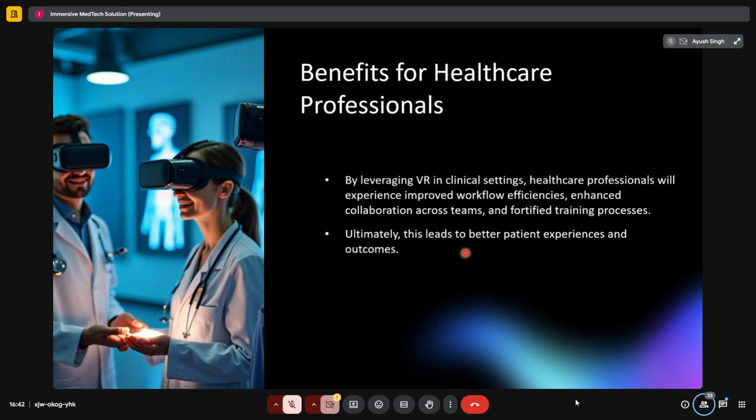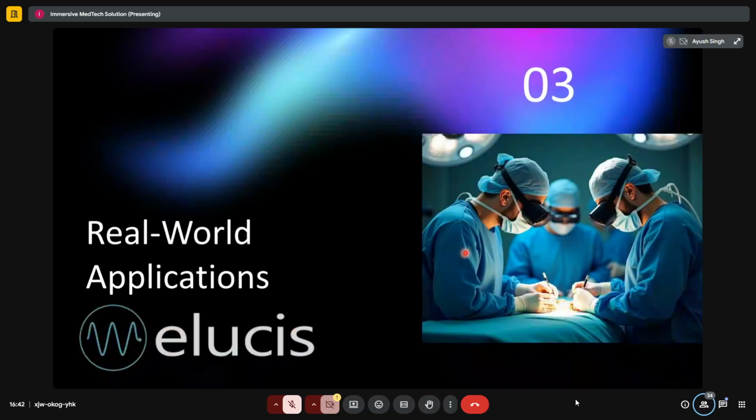After that, we also have certain levels of segmentation. We have low, medium, then high, then ultra. These are different settings that we can select. Generally the preferred methods are medium and high, because the higher the value goes, for example with ultra, we will require a decent workstation which has compatibility with the hardware that we are working on for efficient segmentation.